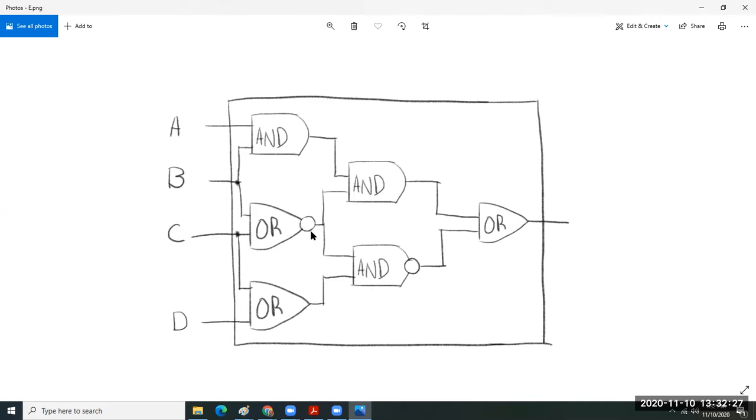This one is tricky because the split's occurring on the second layer. So you have W1, you would leave this W2 and it would feed into the little b for the inside b of this second AND, and W2 would also be the first input here, that little a input for the HDL statement for this, I'm sorry, this NAND. So the term W2 would apply both in this case on the lower input and this case on the upper input. And that's the only thing that would be tricky as far as the HDL. So whoever did this, I hope you're hearing what I'm saying. Then you'd have W3 down here, you'd have W4 and W5. Very nice. I can't wait to see this. I mean, I can't wait to see the truth table.